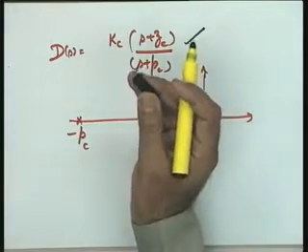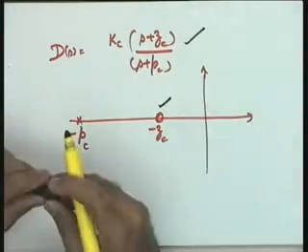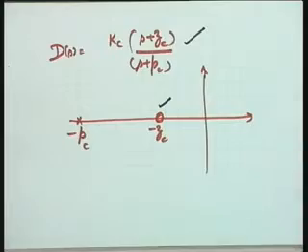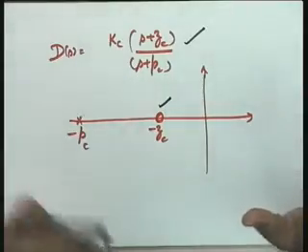A root locus plot nearer the j omega axis is an indication of a situation close to instability, close to oscillations. A root locus plot far away from the j omega axis guarantees a good margin of stability. So a zero at s equal to minus zc pulls the root locus plot to the left, and therefore you should take up phase lead compensation whenever there is a requirement on transient performance.